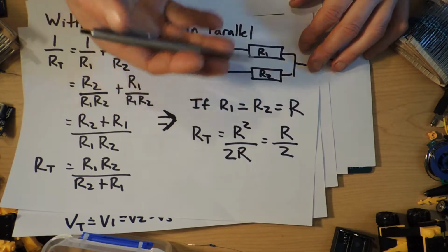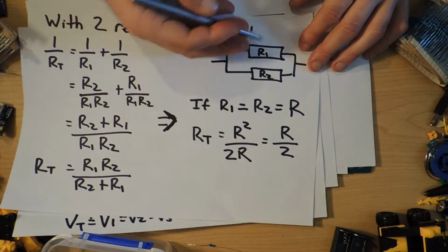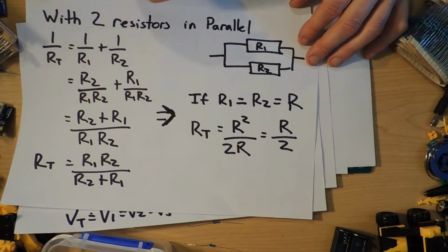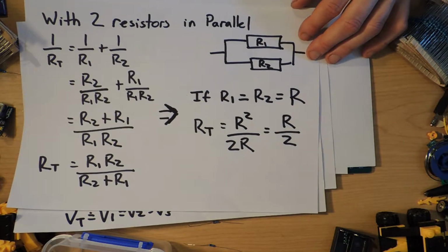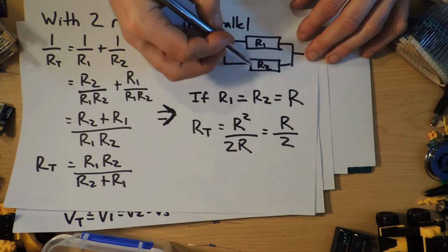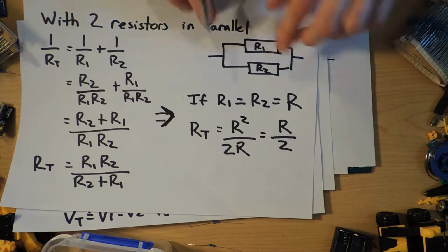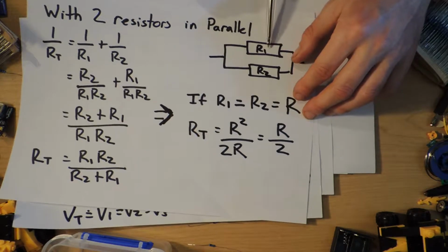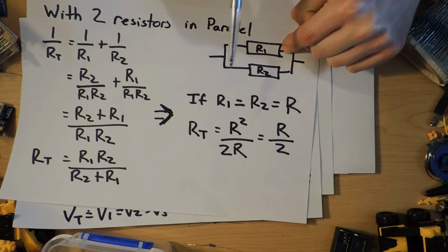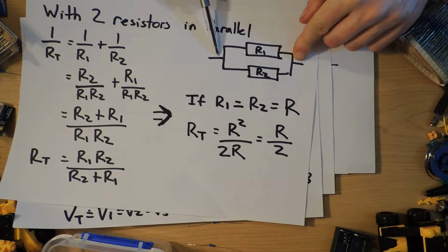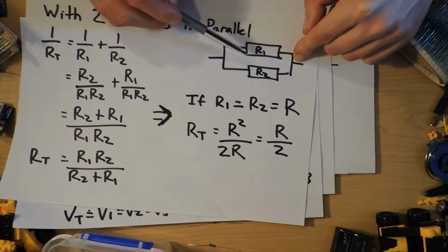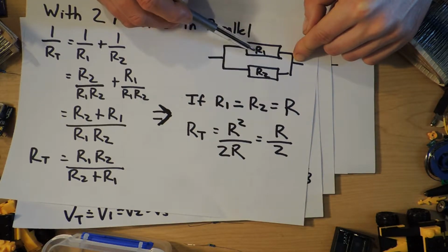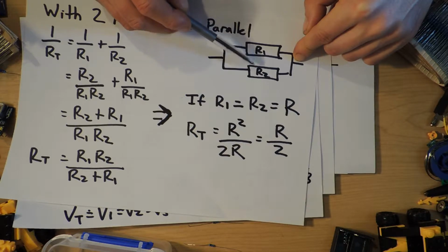It's easier if there are two paths and they're the same to get through than if there's only one path, or if they're different things. Well, that's not true. But the really important thing here that I didn't show is that the total resistance in a parallel circuit will always be less than the least resistance of any of the particular paths.